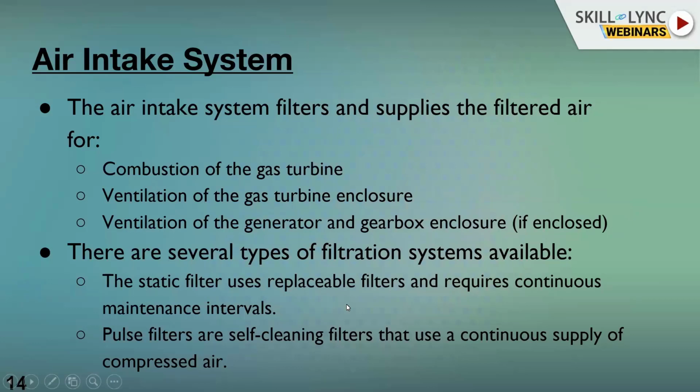Because if you are not able to provide enough air to the gas turbine, it is not going to have enough media to burn the fuel. When there is not enough fuel burnt, that means there is not enough energy generated to drive the blades, and that again results in lower power output.